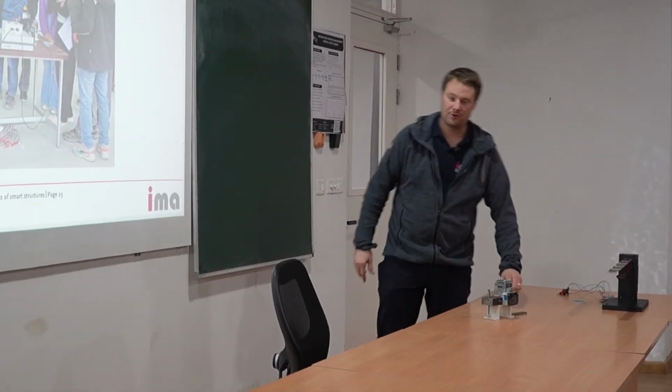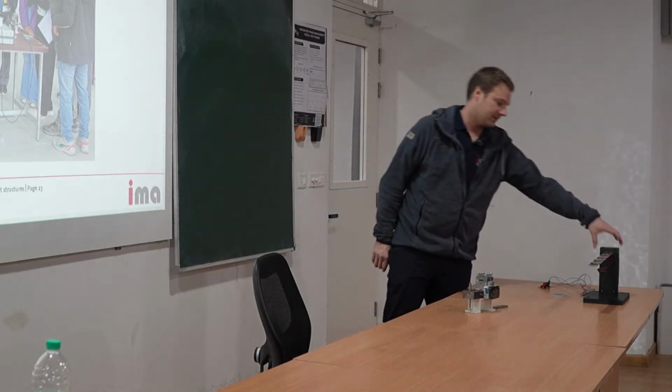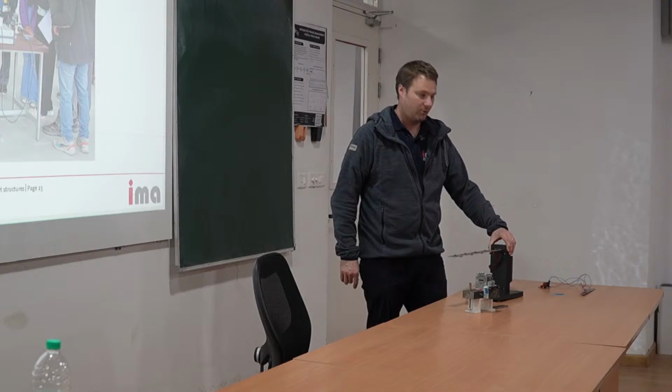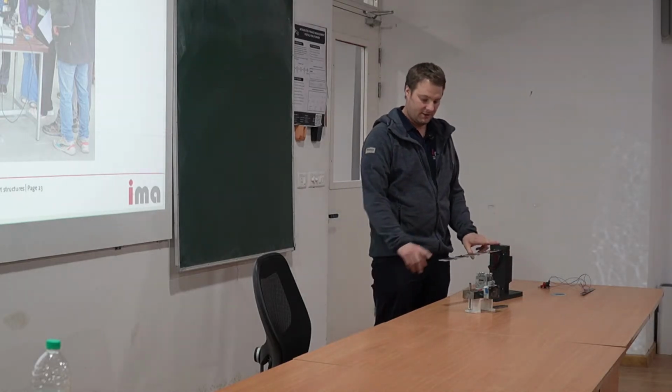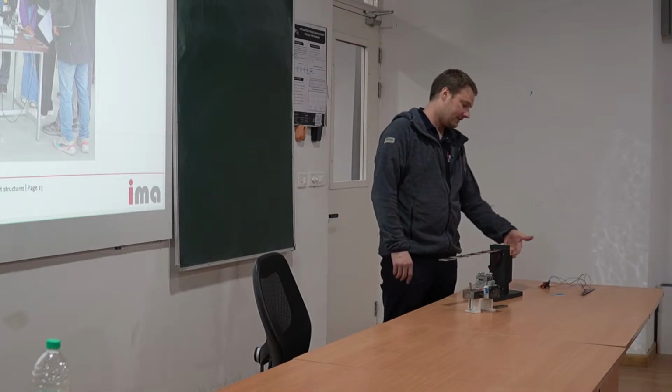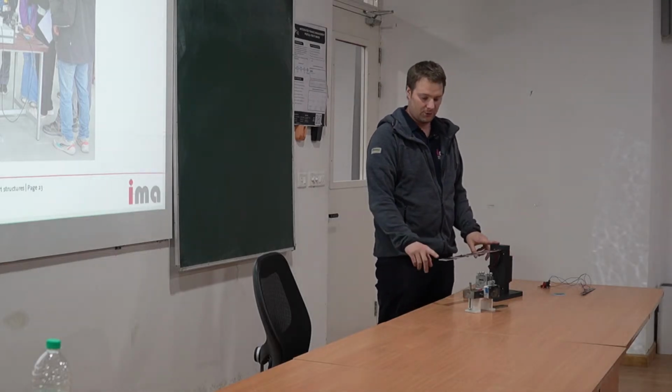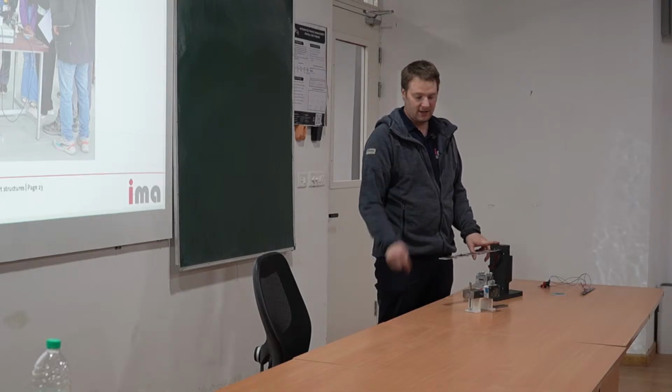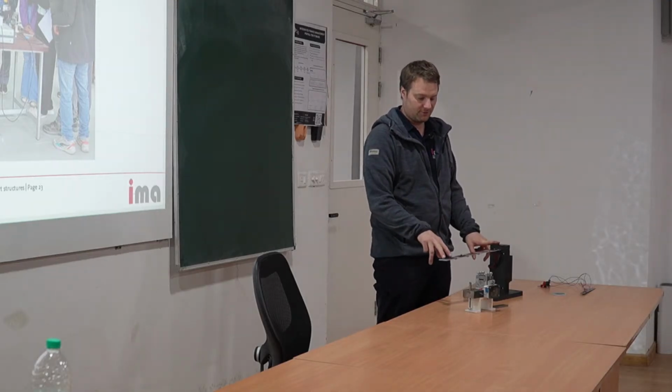You may or may not remember that in all labs we have used piezoelectric material only as actuators, never as sensors, so we use the inverse piezoelectric effect. We never use the direct piezoelectric effect. So, a bit unfortunate, today we could have used the direct piezoelectric effect. What I didn't show you is that if you connect either of those patches, you will immediately see the same thing as the laser distance sensor, because you will see the strain, and the strain will obviously put out the same signal, the same frequencies.